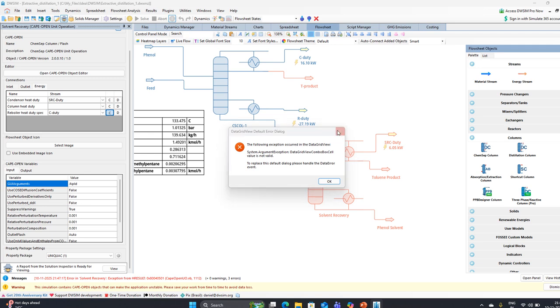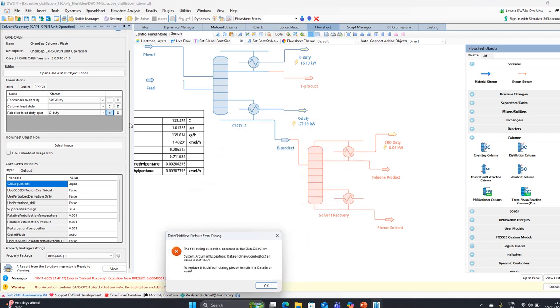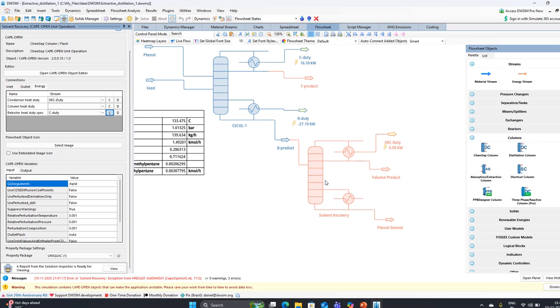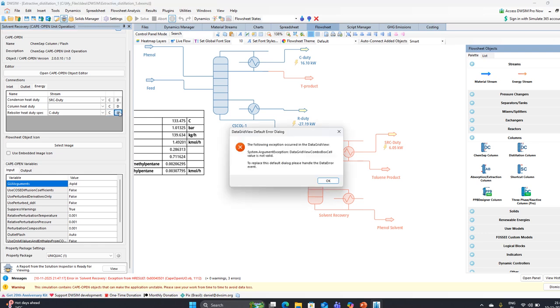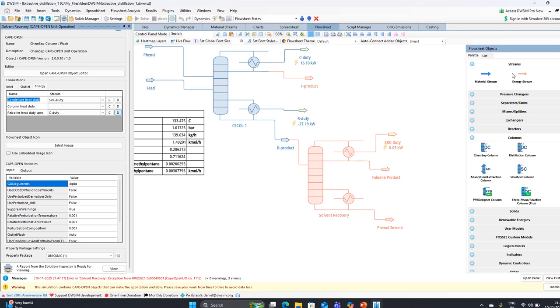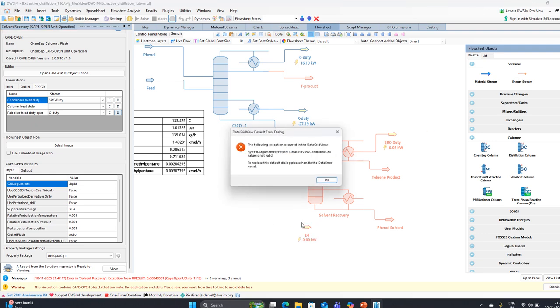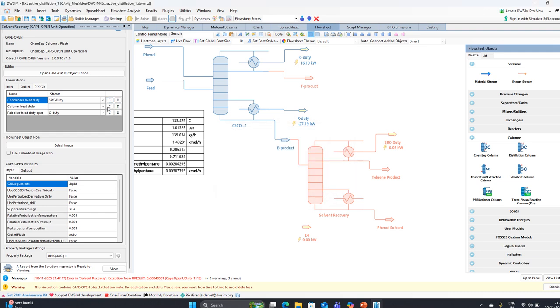I should not delete that stream basically. What I need to do, I need to bring the energy stream. That will serve me the purpose till the time this error is gone.